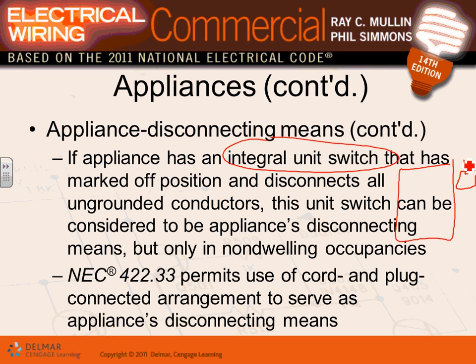I can't emphasize enough, when you deal with electrical equipment, especially 3-phase equipment, always ask yourself, number one, do I have a branch circuit, an overcurrent protection device, and a conductor to feed it?